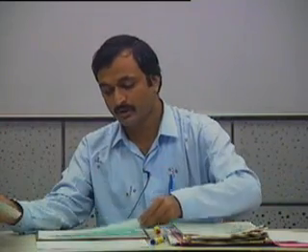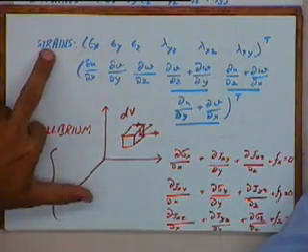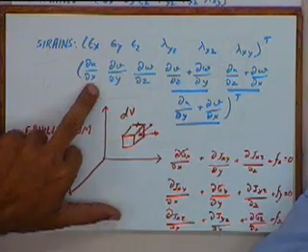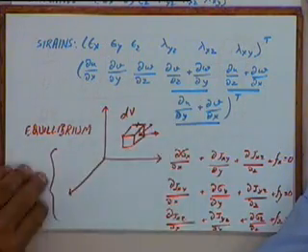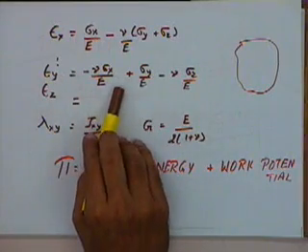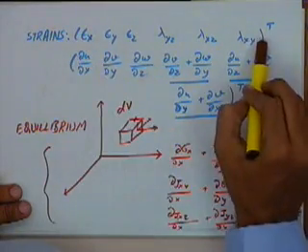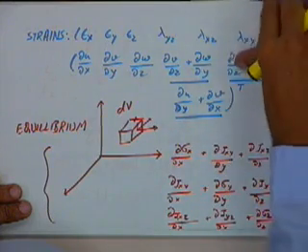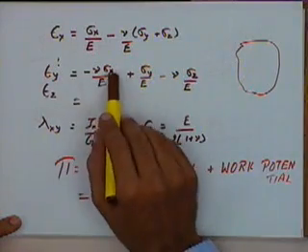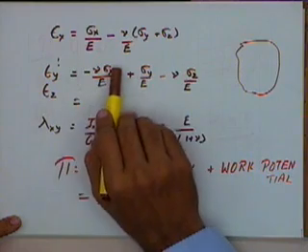Now, if you look at these equations, these express the strains in terms of the deformations U, V and W. Similarly, we have expressed here strains in terms of the stresses. So if I know the deformations, I can get the strains from here. Once I know the strains, then using these equations I can get the stresses.